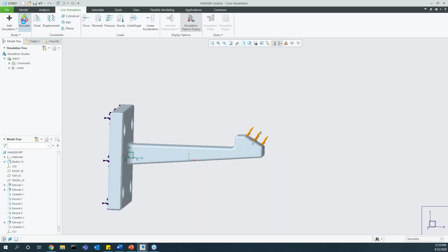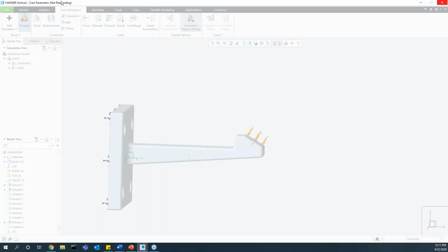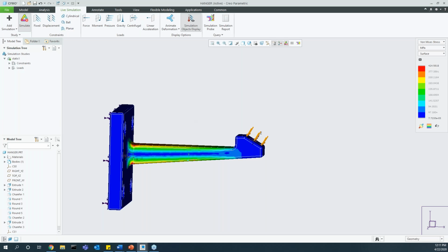Now, if I run a simulation, we can look at the next levels of enhancement, which would be the legend. There it goes. So over on the right, our legend has been better outfitted so that we can quickly switch between results. We now have simple drop-down menus that can let us just switch between something like deformation and stress, for example. This drop-down gives us what units we want to be in. So if we want to go to KSI, we can do that easily.